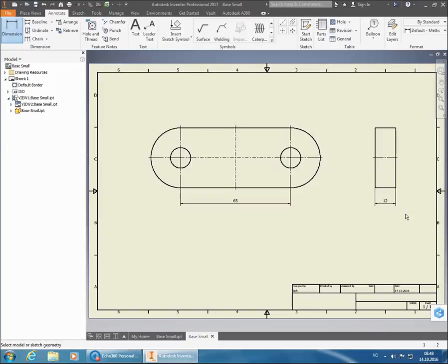And just a small thing like that, it might seem that people are sticklers with details, wanting to have it look like this, but it actually makes the drawing easier to read, because you get these systematic placements of dimensions, and it makes it easier for your brain to process when you're trying to read it. So by avoiding having different heights on the dimensions that can be placed on the same line, that's a better way for your brain to handle the drawing when you're reading it.